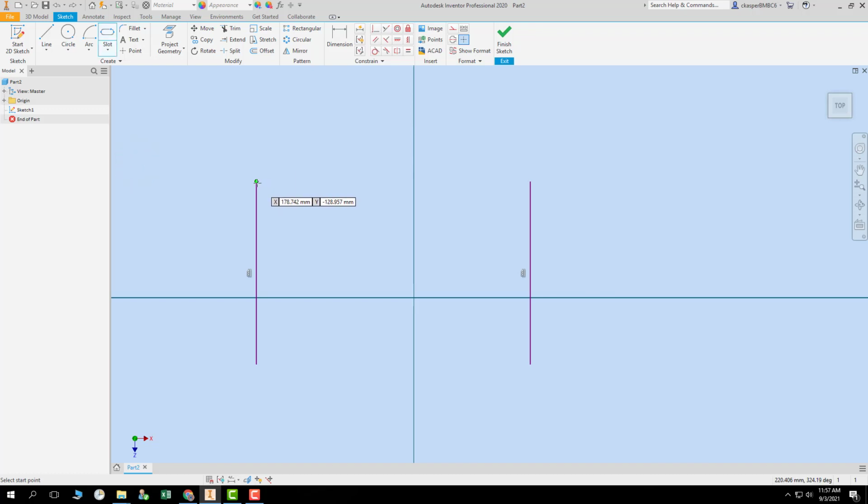overall. I believe if I start here on the end and here on the end, and I go. Notice instead of the center of the circle extending past the lines, this is contained inside the lines. So it's putting a slot inside of an area rather than outside, or using the ends here as center posts. Now they are endpoints. And I click there and that puts it right in there. So they're not extending past the lines on this type of a slot.